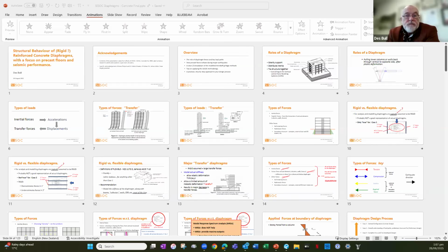Worry about it. For Marco Chui, do you have any advice on where to put the dummy nodes in the strut and tie model? Will it be best to align this with the lateral load resistance system? No, that's actually a good question. It's normally not too critical, but what we tend to do is keep them in the middle, lined up with the center of mass and quite wide apart. Wider apart, the better. It tends to just help stabilize the mathematics.